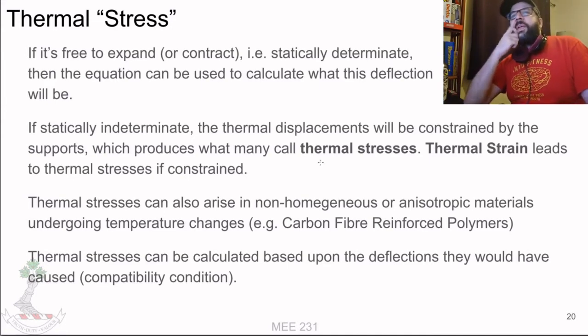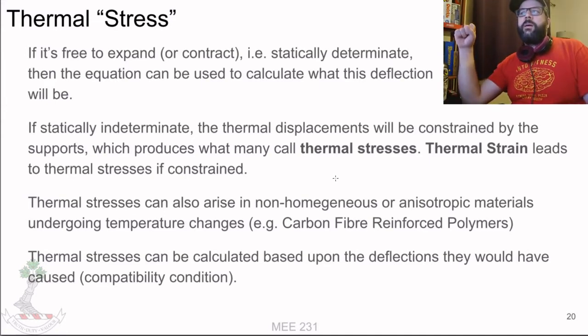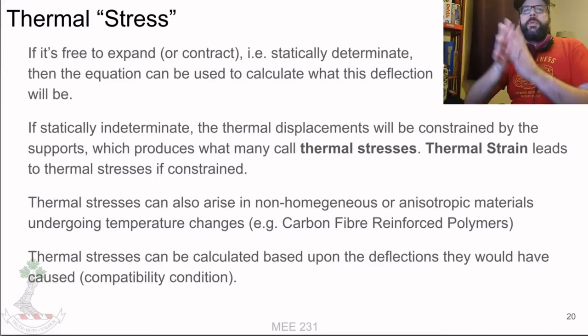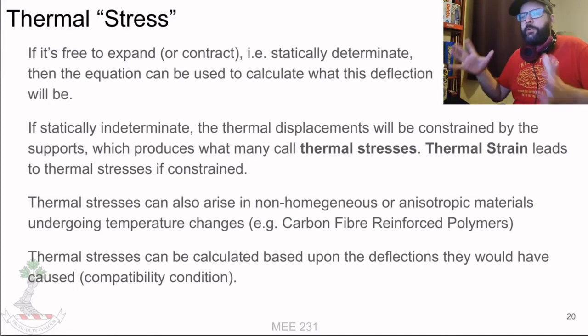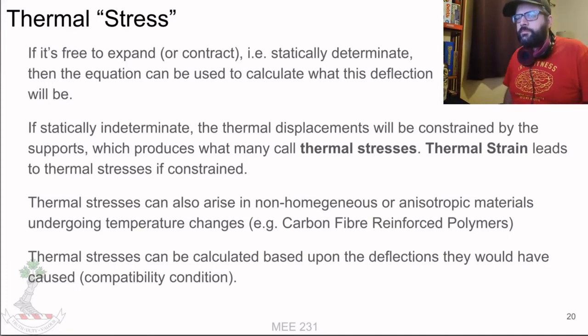So if the thing is free to expand or contract, then you can use that equation to figure out what that deflection will be, and then there won't be any stress induced. It'll shrink or it'll get bigger, and that's all that'll happen. No stress will be induced as a result.